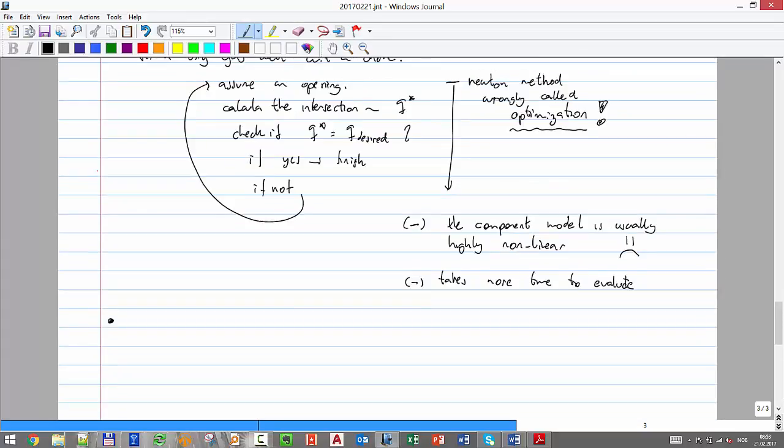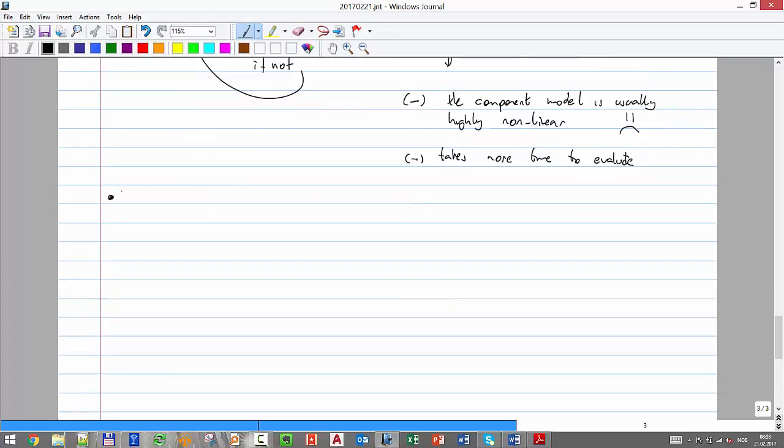Now another comment that I want to make is that the equilibrium rate can be affected. I can affect somehow the inflow and the outflow, the available and the required, right? The operator or the engineer can affect the available and required pressure curves.